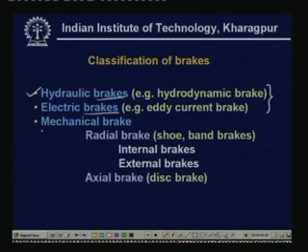Now, mechanical brakes, what we are going to study in these two classes, are mostly mechanical brakes. These can be divided into two parts. One is the radial brake. Radial brake means that the normal force is applied radially. Here we use drum type brakes or cylinder type brakes.